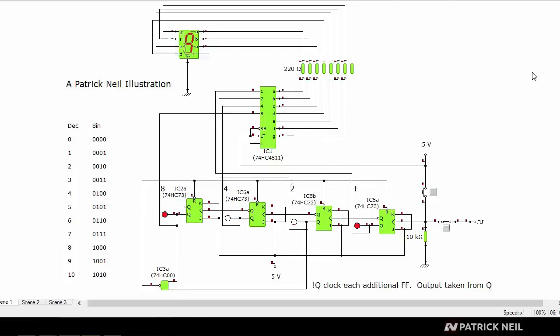The reason we reset the flip-flops to 0 after 9 is because we have one LED, and the LED can only display digits from 0 through 9. So even though the counter is still counting, we cannot use those extra digits after that. If we allowed all that code to go to the decoder, the LED would just be blank and we wouldn't see anything.